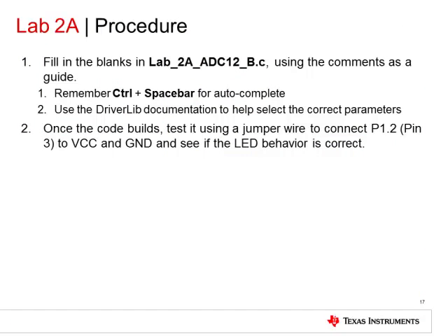To begin the lab, open the source code Lab 2A adc12b.c in the project folder. You can use the comments as a guide and set up the ADC using driver library as explained in training module 4. Once the lab exercise is complete, you can test your code by tying the ADC input channel to VCC or ground to check whether the LED turns on or stays off.